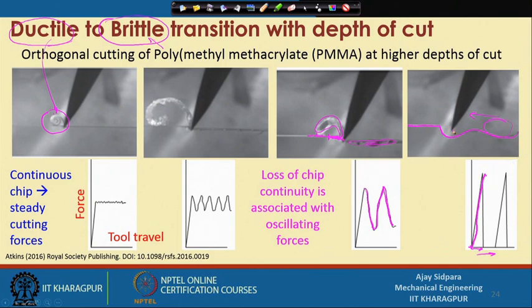Now, in this situation, you are getting an off time, that means the tool is not in contact with the surface. So, this is the non-contact region. Your tool has removed this much amount of material, it has scooped out this material, and then the tool comes into contact again. So, after the off time, again you will get the same peak and the same fashion of the first trend, and again you are getting this removal.